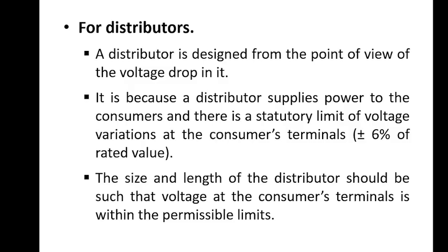All right. This slide also explains the design consideration for the distributors in the distribution systems. Unlike feeders, a distributor is designed primarily based on the voltage drop rather than current carrying capacity. This is because distributors directly supply power to customers, and voltage at the customer's terminals must remain within specified limits. There are some regulations that restrict voltage variations, typically within plus minus 6% of the rated value.